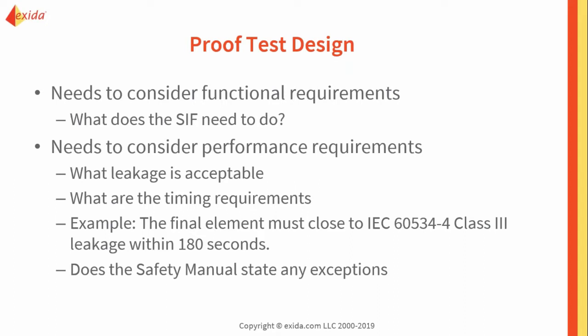And then after that, you need to look at what the performance requirements are. Things like, is leakage acceptable or not? What are the timing or response requirements for the SIF? Depending on your situation, your plant, your SIF, leaking may or may not be an issue of concern for you.